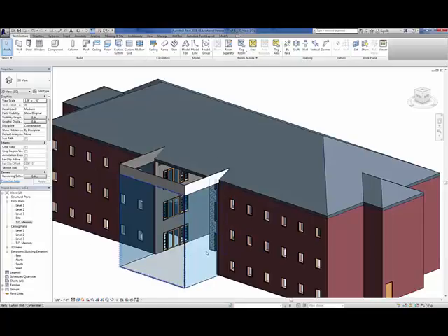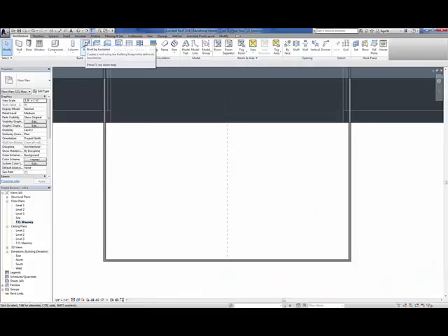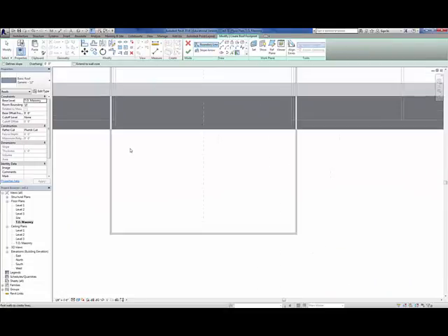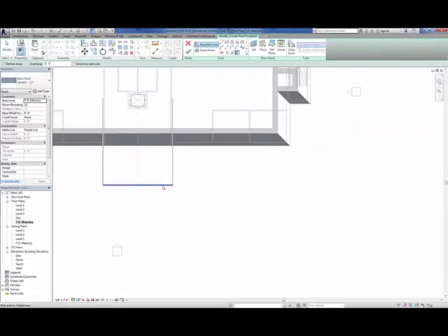All right. Now we'll go back to our top of masonry. Go to our roof. And again, we can use roof by footprint. One thing we need to do though this time is because now the top of this wall is 4 feet above the top of masonry level, we need to change our base offset to 4 feet. That way it's creating a temporary plane 4 feet up that we're going to work on. So select that one. Nope, go back. And I need to turn define slope on to have slope on these guys, and then I'll turn it back off to draw the line. That's the back edge.